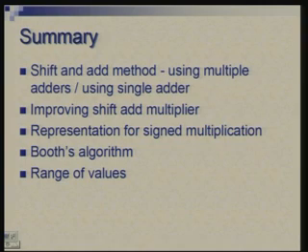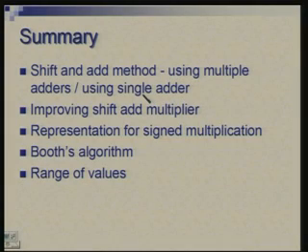So, this we could translate into a circuit which had one adder for each partial product, and then we wrapped it around, put that in a sequential iterative process where the same adder performs addition of various partial products. Okay. Then gradually we made certain observations and tried to improve the circuit.